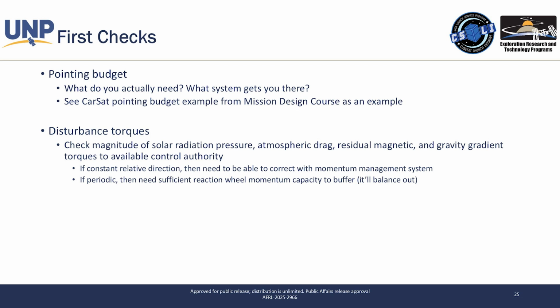Atmospheric drag, it does matter. The more symmetrical your body is, the less it probably matters, depending on what attitude you have relative to your velocity vector, into the motion of where the air is hitting you. What residual magnetic fields you may be having or generating can torque you if you're close to Earth. Gravity gradient torques, not a big deal on small sats, but can matter for larger structures. So like Hubble Space Telescope, the space station.